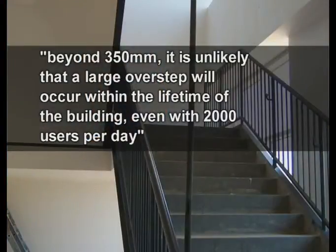What's the thinking behind this? It came from research, basically, that it was perceived that slips were caused by overstepping. And that meant that people were only really achieving 50 or 60% of the surface of the foot on the actual tread. So the outcome of that was that with a 350 millimetre going on a stair, that dramatically decreased the potential for slips on stairs.